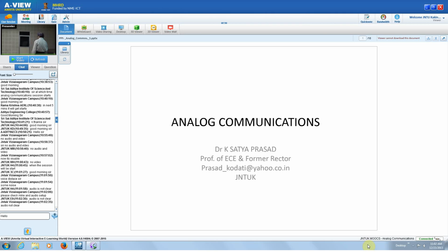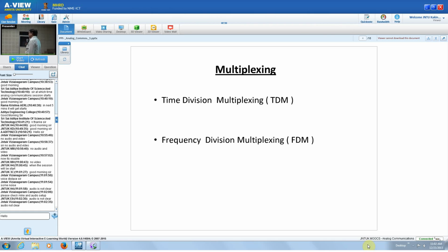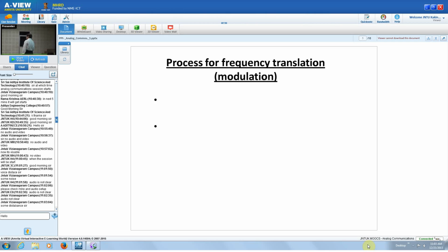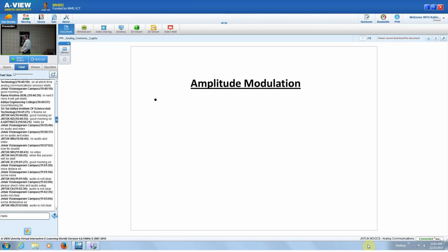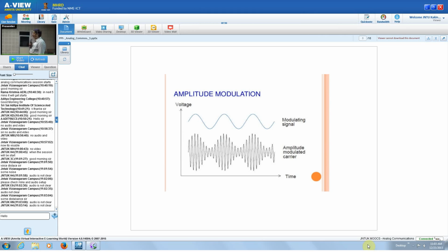A normal frequency translation that we have seen is going to be a linear one. So if the spectrum of the baseband signal contains two spectral lines, then it is going to be double. If we have 6 spectral lines, then we get 12 spectral lines and so on. Whereas if we have the baseband signal from 0 to FM, with FM the highest frequency component, then the frequency translated signal will have frequency components from FC minus FM to FC plus FM, so that 2 FM will be the bandwidth that we are going to have.